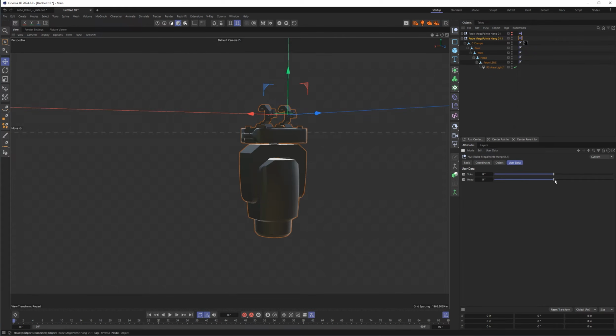And now you can see that this one has now come into kind of where we want it to be, just like the yoke, where if I go back and forward, and also this is now limiting my rotation so that I can't actually tumble the head through the neck of the yoke there. So this is great. So there you go. Now we have our rotation all set up for the yoke and the head, and these will just always work together any way that you want.